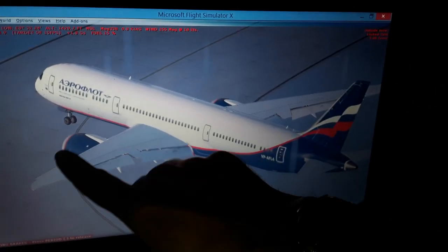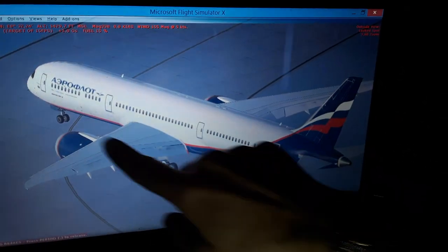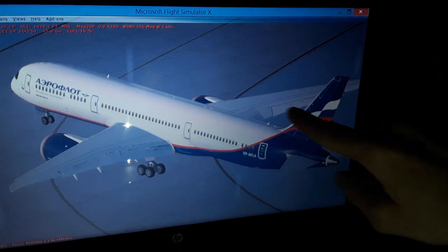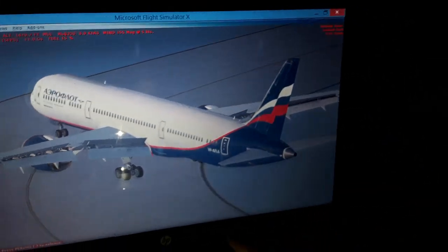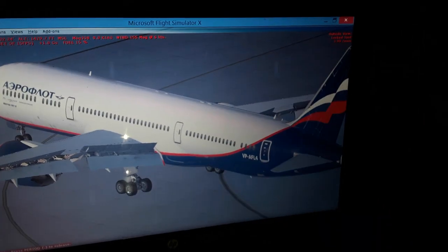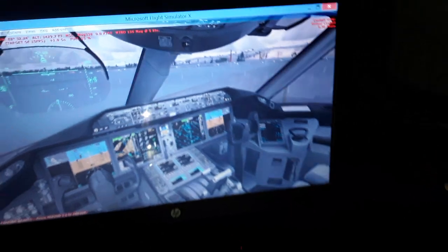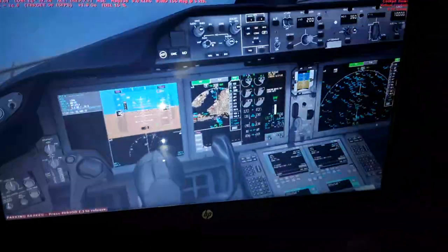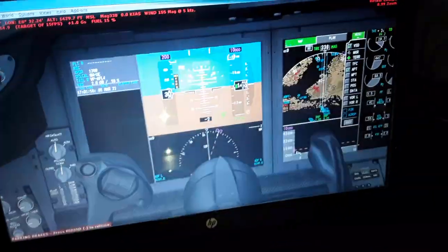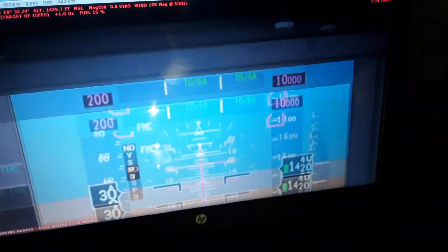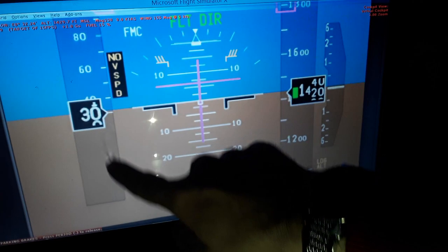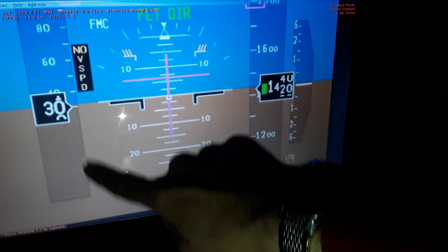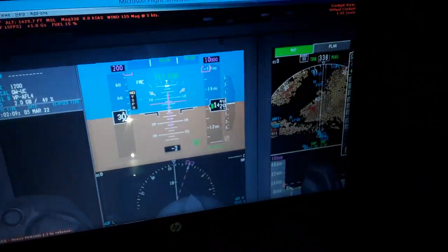So you can see also we have the aerodynamic chord. Also we have the stall. The airflow becomes detached above the top surface of the wings when we fly. So you need to monitor over here in the primary flight display where the airspeed is indicated. You can see the airspeed here, the airspeed tape. So I'll talk to you about these things now. Airspeed indicated. You can see the stall speed displayed with an amber and red indication down here when you fly.